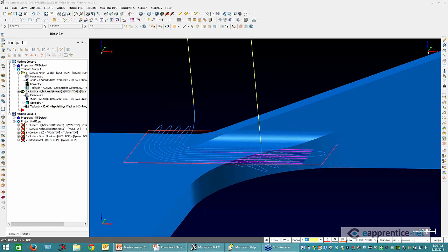Basically, if it can't do your smooth connection, it's going to default to broken, because the algorithm runs and tries to calculate all of these different tangential positions, and it just says, you know what, I got pretty close, but the end point of the calculation for my smooth linking ended up here and the start point's over here, and it just defaults to broken. So you kind of need to play with those settings and massage them to get what you're looking for.